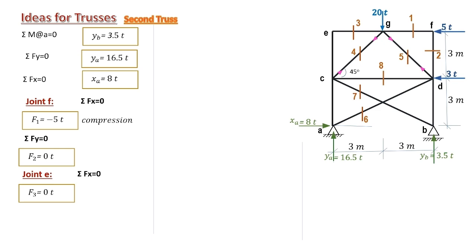Generally, we take one in the X direction and one in the Y direction, maybe considering one joint and the section, whatever you are comfortable with in the solution of your truss. Here is joint G, and we consider equilibrium in the Y direction to get a relationship between internal forces in members 4 and 5. Please note, even if you do not need to extract the joint outside, it is good practice to apply the arrows indicating tension force on the members you are calculating.